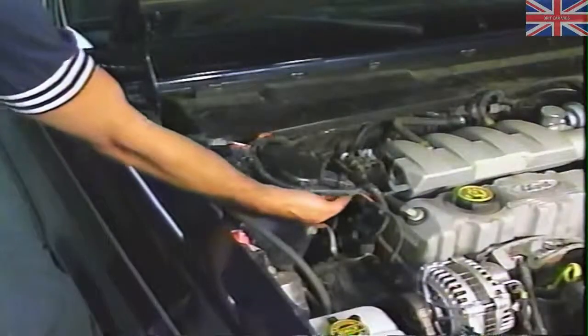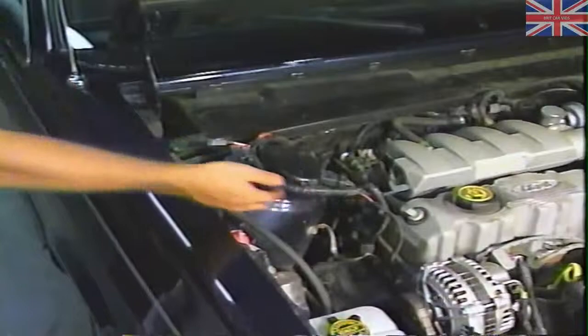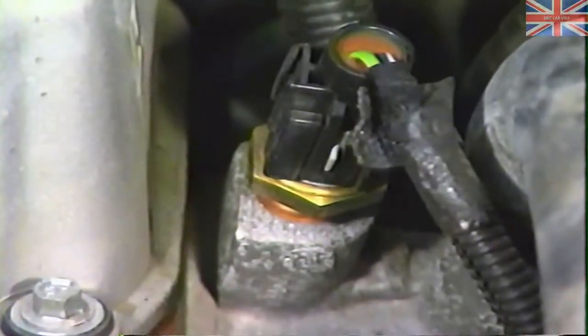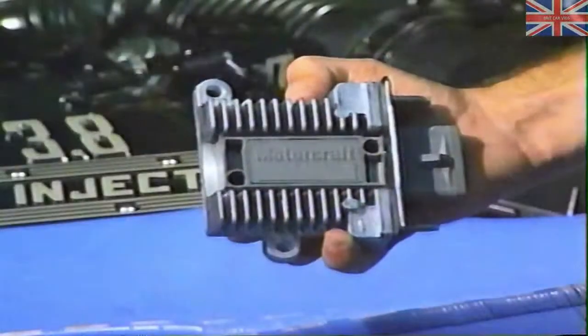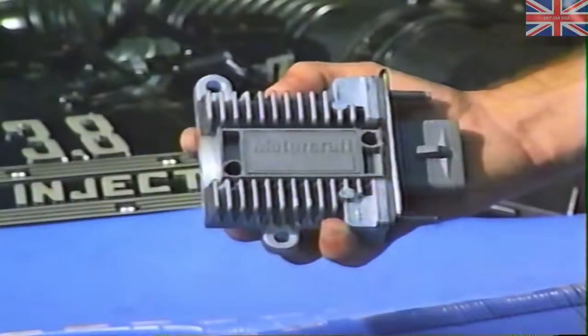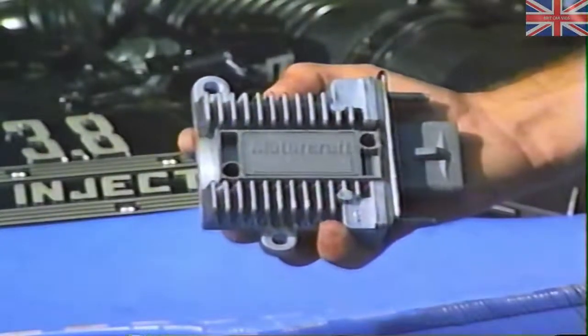One feature of this system is that if the ECA assembly becomes damaged electronically, or if one of the primary timing control sensor inputs to the unit malfunctions, the TFI module will allow the ignition system to operate in a fixed or base timing mode, as long as the PIP signal is still being received by the TFI unit.